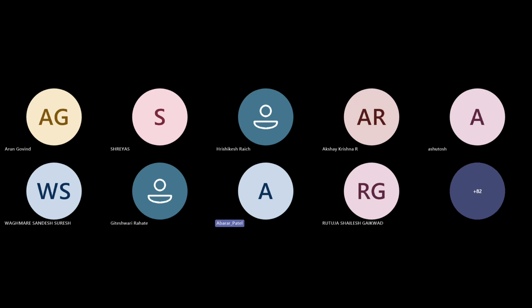If the vendor has not given a circuit diagram, you can find that on the internet. Circuit diagrams for certain BMS can be found online. If there is no requirement of current capacity on your auxiliary pack, you need to do your auxiliary load calculations, and based on that, you need to find the exact capacity of your auxiliary pack.